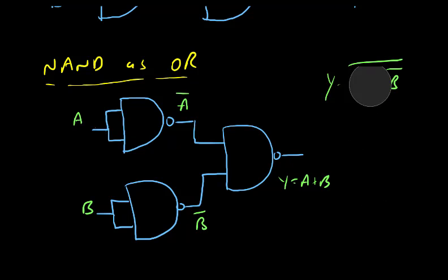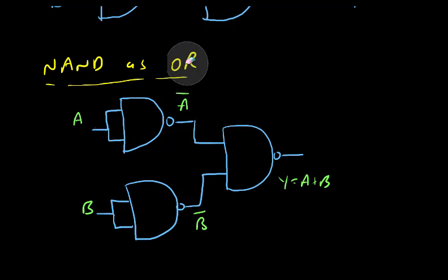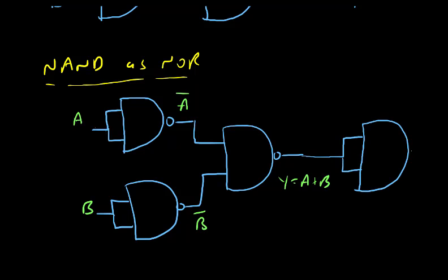So up to here it is working as an OR gate. Now how do we make it a NOR gate? For that purpose, you can even guess it, because you just want a NOT gate after this. So how to draw this NOT gate? This is given to another NAND gate whose inputs are shorted. This particular gate will work as a NOT gate.